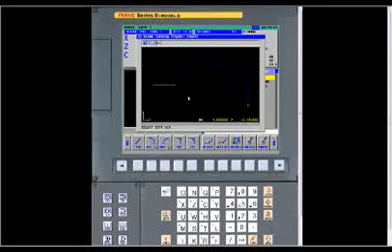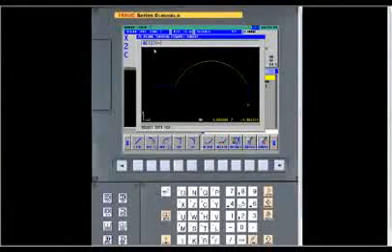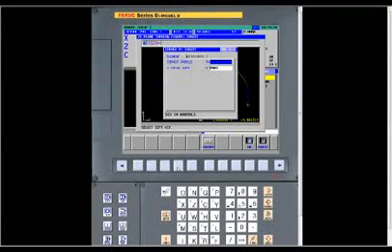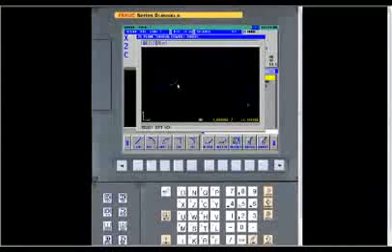Now at this point, we say, darn it, we forgot at the end of this radius. And you see up here at the top, it's showing all the different elements we're describing. At this point, we know that here, I'm supposed to put a radius at the corner of that, but I ignored it intentionally so we can go back and add it to show you how easy that is to do. So we know there's supposed to be a 1/4 inch radius at the corner there. So we put 250, enter, and then say OK. And see, it immediately adds the radius.